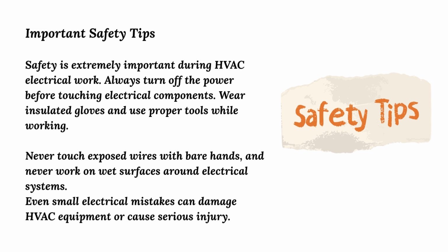Important safety tips. Safety is extremely important during HVAC electrical work. Always turn off the power before touching electrical components. Wear insulated gloves and use proper tools while working. Never touch exposed wires with bare hands, and never work on wet surfaces around electrical systems. Even small electrical mistakes can damage HVAC equipment or cause serious injury.